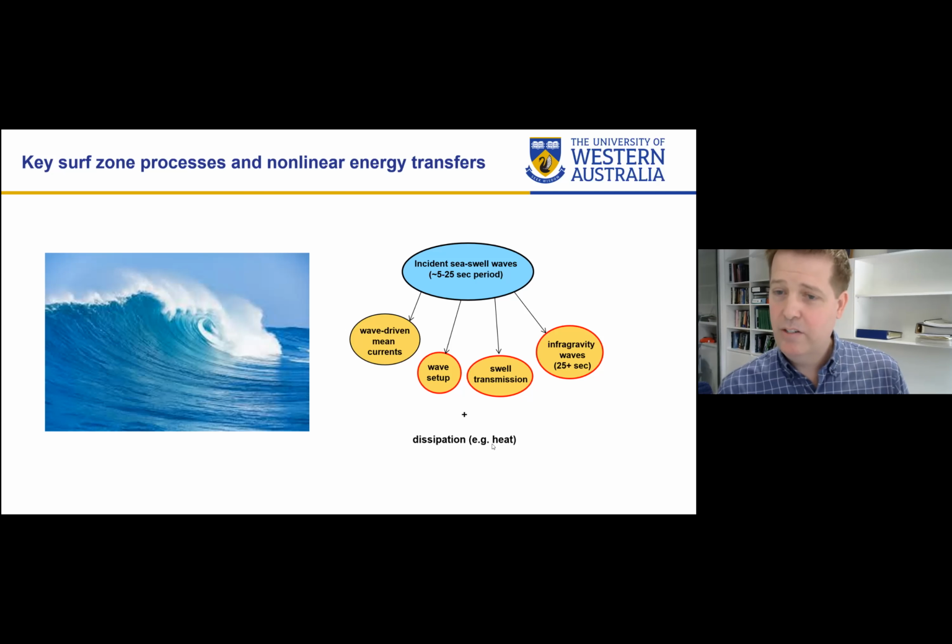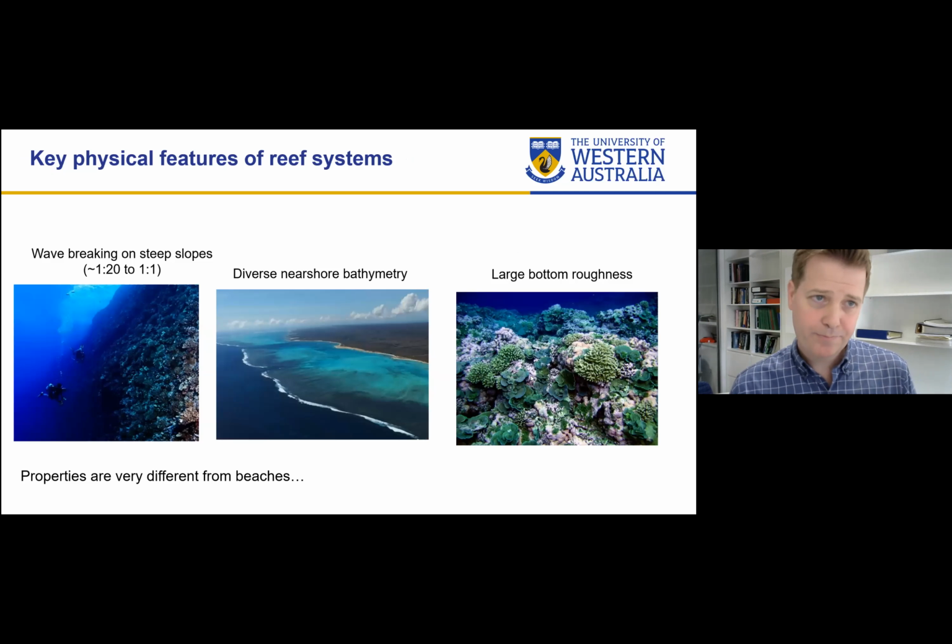Only a very small fraction goes into kinetic energy associated with driving mean currents, and wave setup, which is the rise in the mean water level. Some of that sea swell wave energy is transmitted to the shoreline. And then also the excitation of these infragravity low frequency wave motions, which can have periods of 25 seconds to several minutes. And so I'm really going to be focusing on a lot of these aspects.